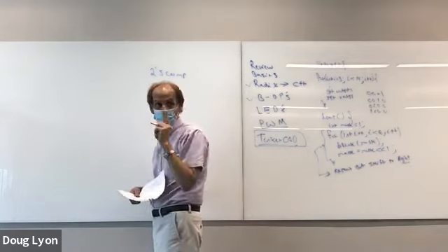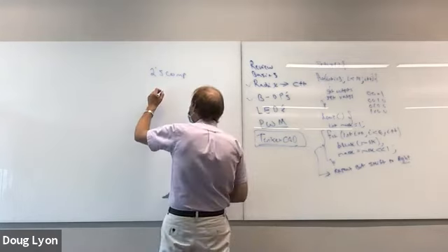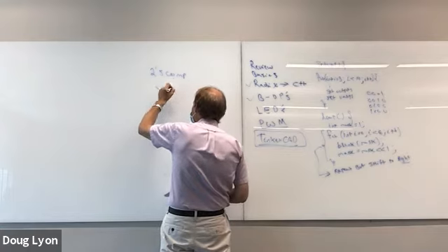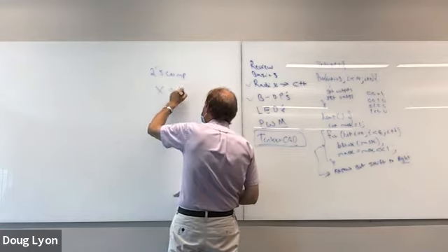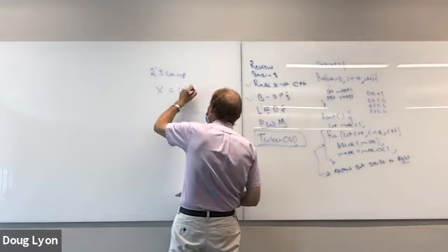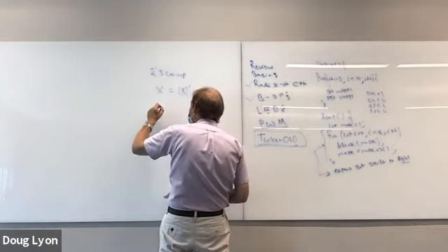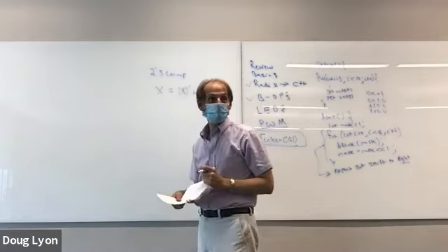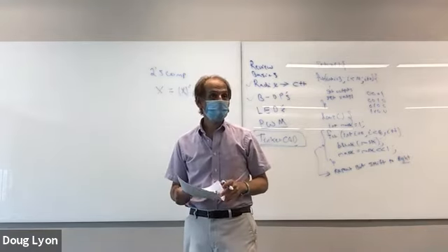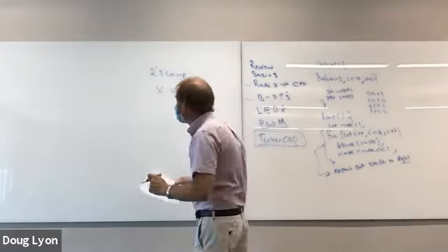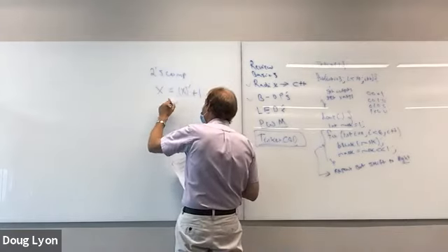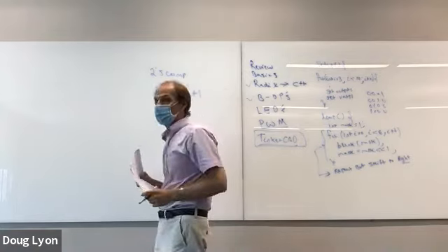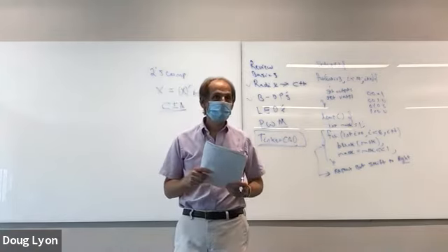If you wanted to form the 2's complement of X, you would invert it and add 1, and that would negate X. Complement and increment the accumulator is a basic instruction in the PDP-8 from Digital Equipment Corporation, circa 1967.